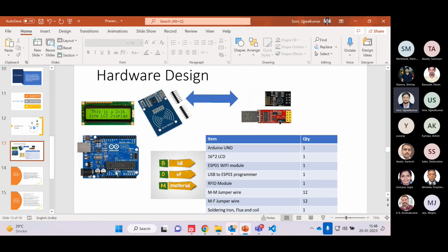And see, we are using a trigger mechanism. So it's not always communicating with the AWS IoT. Okay, it only communicates when a new card is detected. So whenever you scan this card at the scanner, only then is it going to communicate with the AWS IoT, get the data from DynamoDB, and print out this message. Otherwise, the device will be idle.